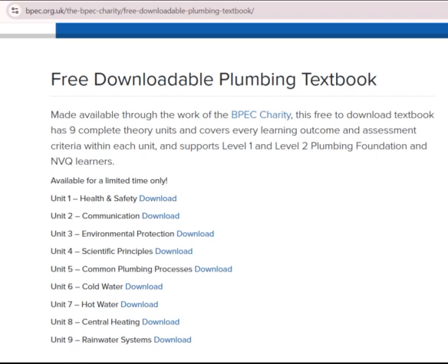AC 5.1. State the procedures required to assemble valves to radiators and mount radiators on wall surfaces. Before the radiator is hung on the wall, dressing a radiator. Dressing a radiator involves preparing the radiator ready for hanging by positioning the valves, the air release valve and the blanking plug. The process is: 1. Remove the radiator from its packaging. Inside the packaging are the radiator brackets, the air release valve and the blanking plug. 2. Take out the factory-fitted plugs.